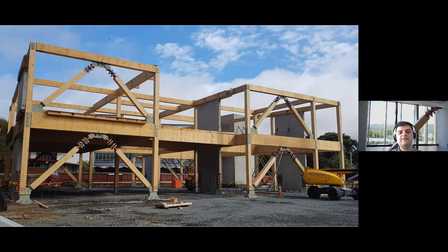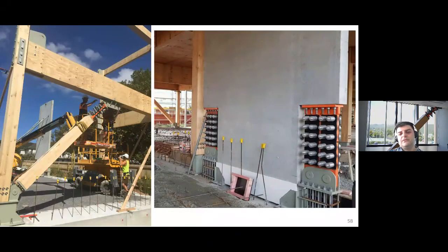So this gives you a good view. K-braces, 7-5 braces in one direction, rocking concrete shear walls in the other direction. The brace test that I showed you a few slides back at AUT was related to this project. More photos. This was an IL4 building, and the designer was able to achieve ductility of 2 with all the SLS1 and SLS2 requirements.